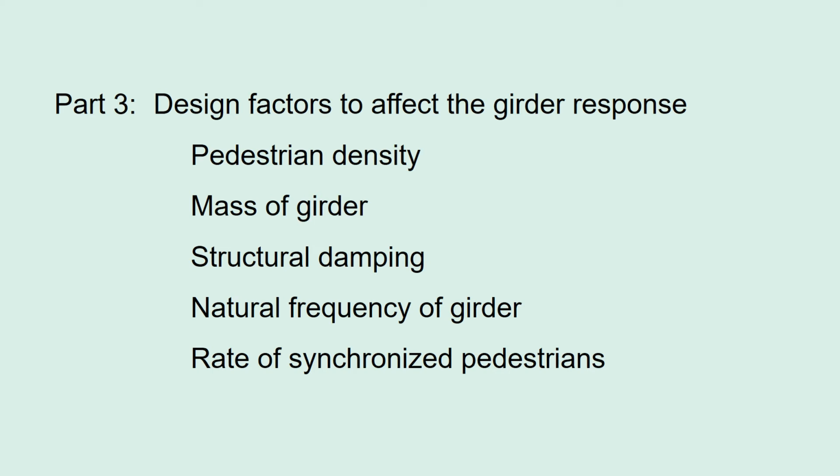Now part 3. Design factors to affect the girder response. I wanted to find a method to estimate the response caused by pedestrians. It would be helpful when you design a footbridge. The response induced by people depends on pedestrian density, mass of the girder, its structural damping, natural frequency of the girder, and rate of synchronized pedestrians.